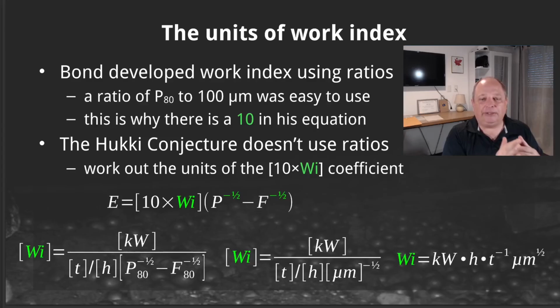So if you look at the units in the third theory equation and just crank them through, you end up with a new set of units for the work index that are distinct from specific energy consumption. And that's important because I see numerous examples of people trying to do mathematics with work indexes and add them or subtract them from specific energy consumptions, in the erroneous belief that the two quantities with the same units are somehow additive.